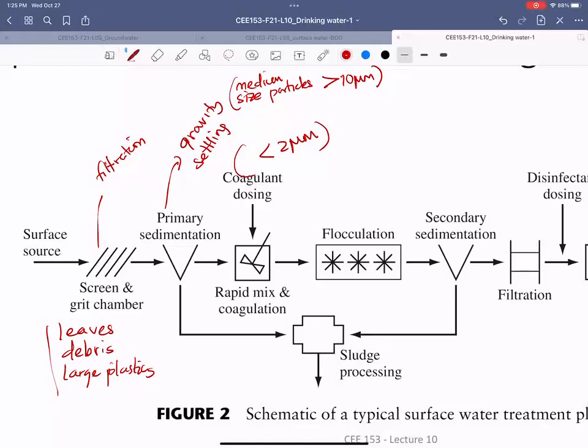So how do you make coagulation? You add certain chemicals, which we did actually in the beginning of the class. In fact, next class, we'll have a demonstration for this treatment, so you can see how it works. We'll add the coagulant, which is basically iron chloride. Last time we did it, and you see this is kind of red color, but this time we'll also show how to remove that red color, by adjusting pH. I just want to explain this class theoretically today.